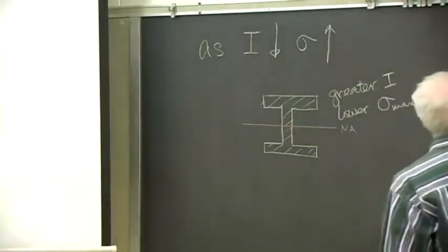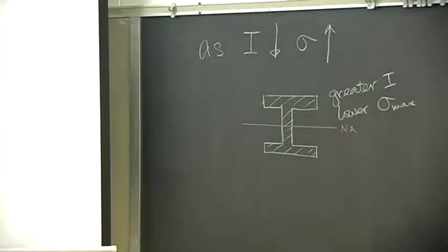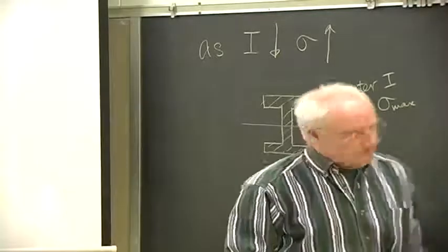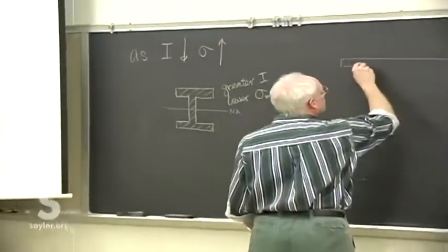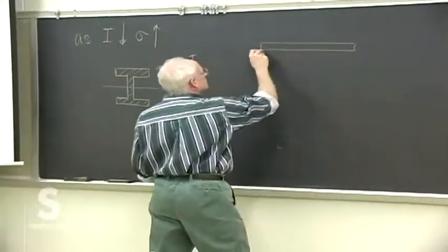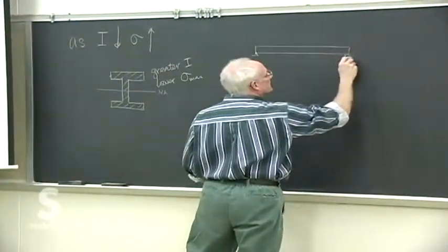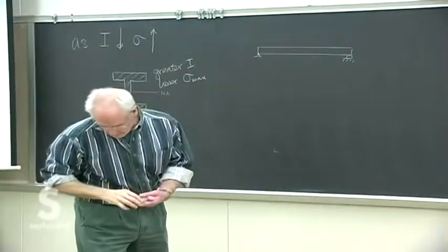We could have done a rectangular beam, but those are very heavy. This is much lighter, with a relatively greater moment of inertia. So that's very, very useful to use I-beams. So, real quick calculation with it.